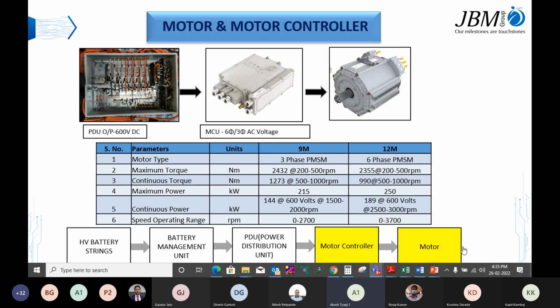And if you talk about losing magnetism of the rotor of synchronous motors, first of all, we are providing water-based cooling. And then certainly logic is built inside it, like if the temperature is going to rise above this value, then the motor will shut off.